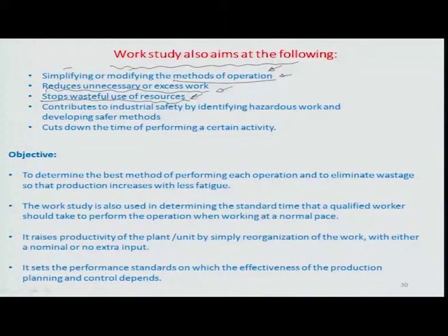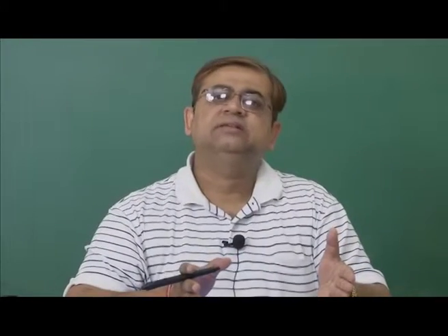For example, I was exemplifying yesterday the assembly line and a practice where covers are put on all four sides of the automobiles to prevent the doors from getting dents during the assembly operation. The option that was suggested is that if the door sub-assembly can be made separately by pulling out the doors at the painted body stage, and then separately supplying them to the final line where the doors are assembled back, this whole problem of using extra covers, extra material, maintaining those things, material movement related to those things and employing different manpower could completely be eliminated.